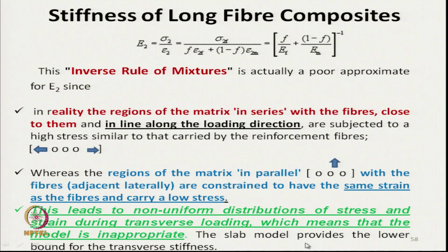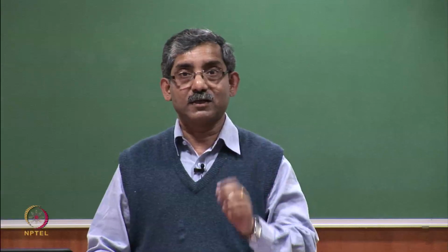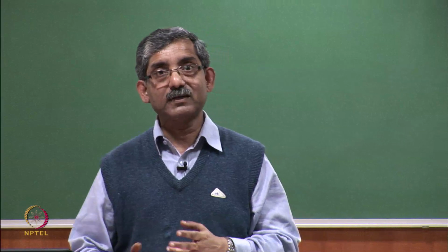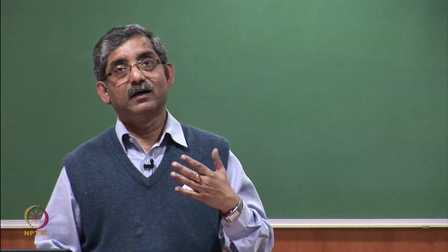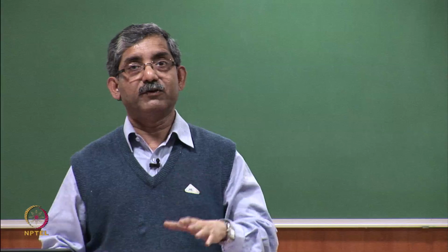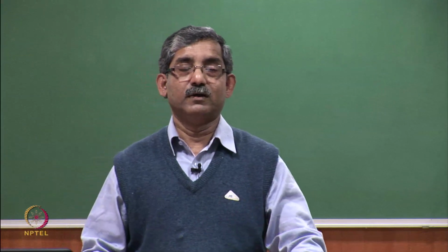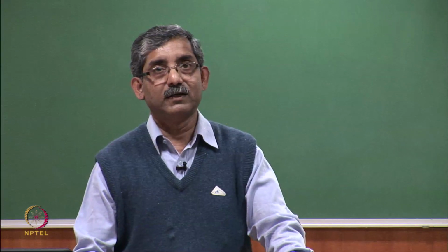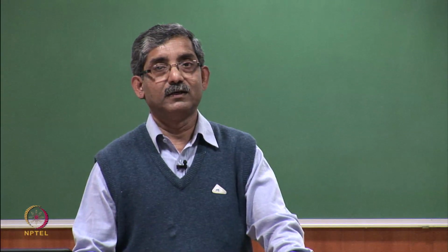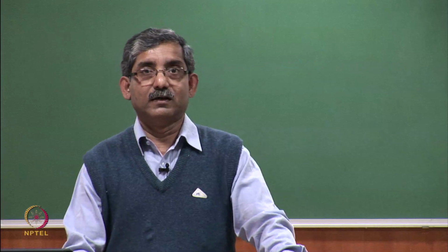The slab model provides a lower bound for the transverse stiffness. So, transverse stiffness measurement is difficult by this type of model, but it predicts the longitudinal stiffness well.